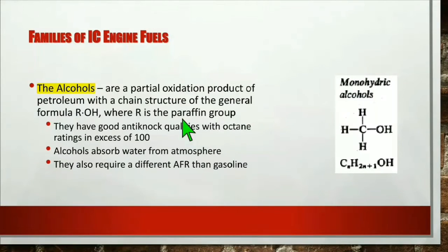Next one, the alcohols. The alcohols are a partial oxidation product of petroleum with a chain structure of the general formula ROH, where R is the paraffin group. They have good anti-knock qualities with octane ratings in excess of 100. Alcohols absorb water from the atmosphere. They also require a different AFR than gasoline. And this is the chain reaction of monohydric alcohols, CnH2n+1OH. This is the basic formula of the alcohols group.